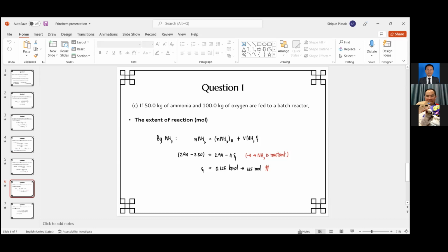That's right. And also you can calculate the conversion by the oxygen: initial oxygen minus final oxygen, divided by initial oxygen, multiplied by 100, and you get percent conversion. Percent conversion means the amount of oxygen converted to the product. Mostly when you calculate the conversion, you calculate based on the limiting reactant, because oxygen is the limiting reactant here. Okay, thank you for your presentation.